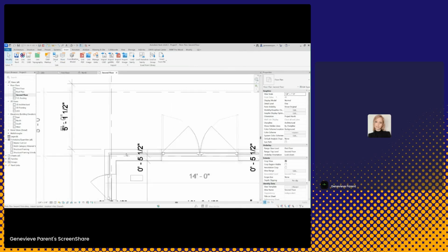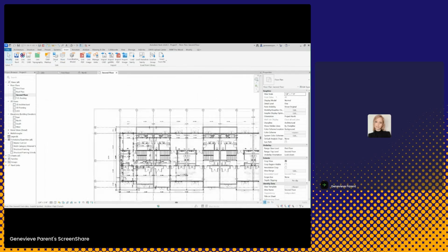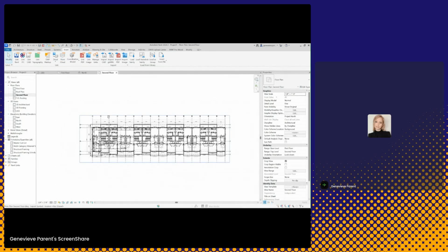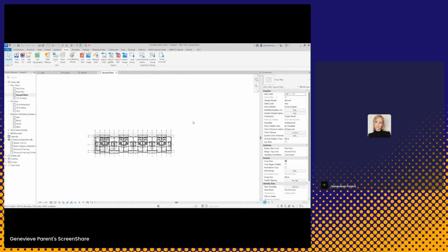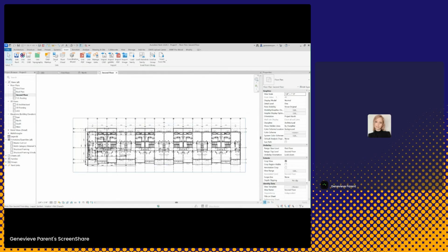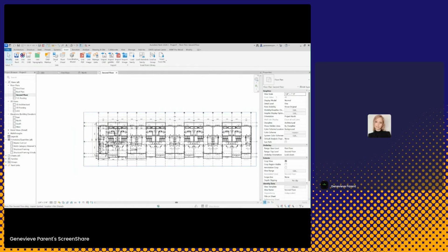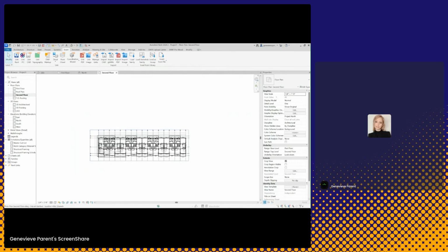They don't always come in aligned for the simple fact that if you're working from an AutoCAD drawing and you have all of your floors in the same file with all of your elevations, all of your detail sections, what happens is if you had this all in one file, you would bring it and you would have your entire file on one floor. What's best practice is to go into your file and separate them, keep them separate, and keep them on the same origin point. Like that, they are going to come in automatically stacked properly.